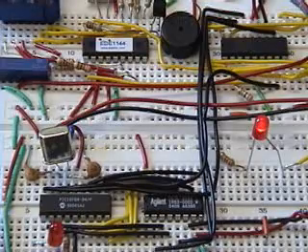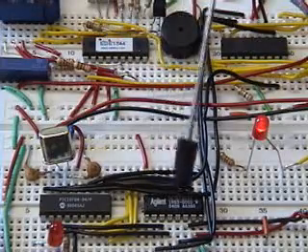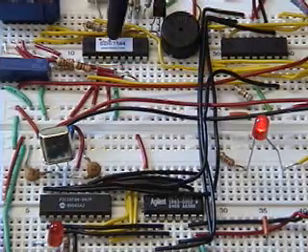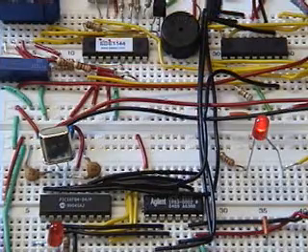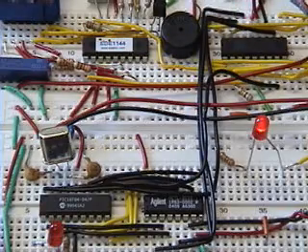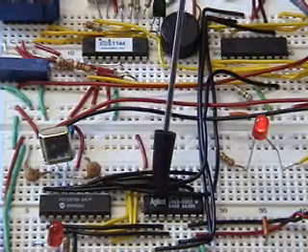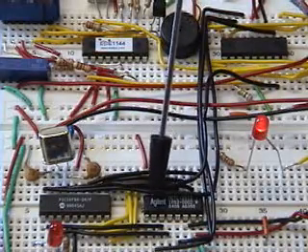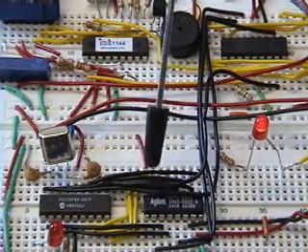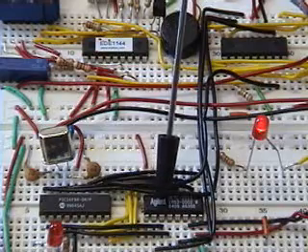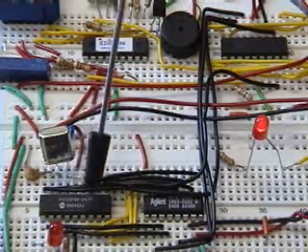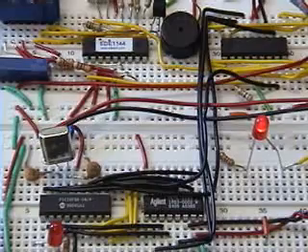There are two specialized integrated circuits that are used on this protoboard. The first is a keyboard encoder that allows us to directly input data from the keyboard to the microcontroller. The digital encoder on the motor is coupled to the microcontroller through a quadrature decoder and counter that provides data that can be directly read by the microcontroller.